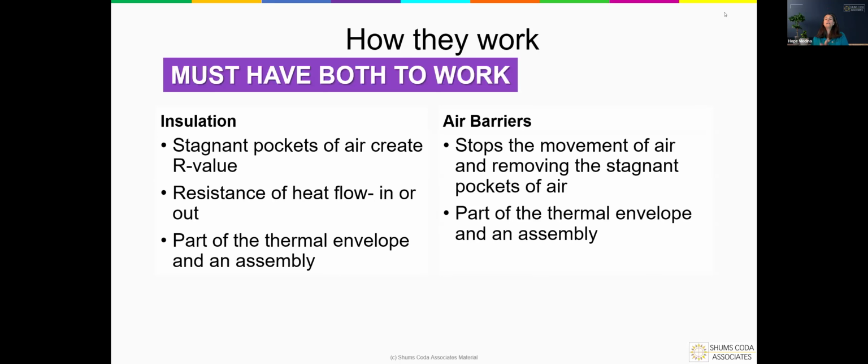So the idea is wherever you see insulation, when it's part of the thermal envelope, then you should always have an air barrier with it to make sure that the system works together.